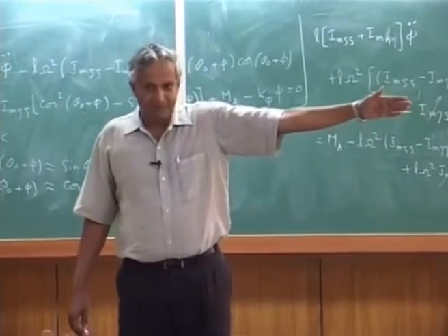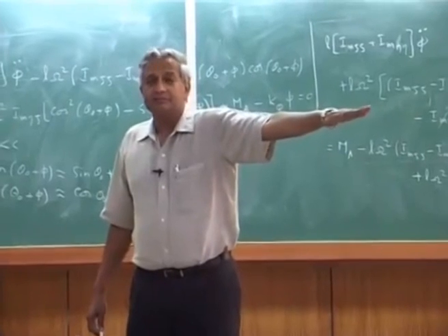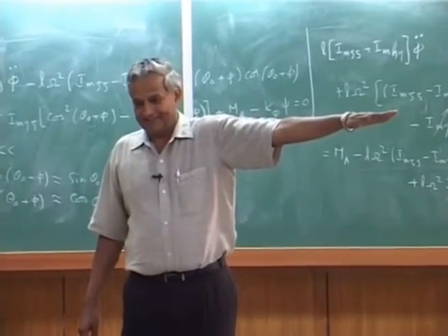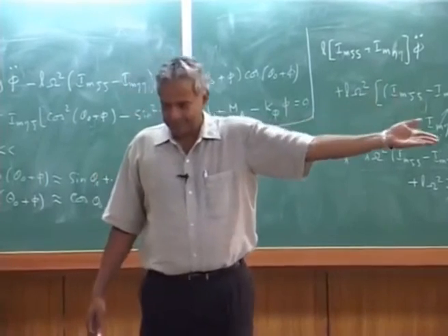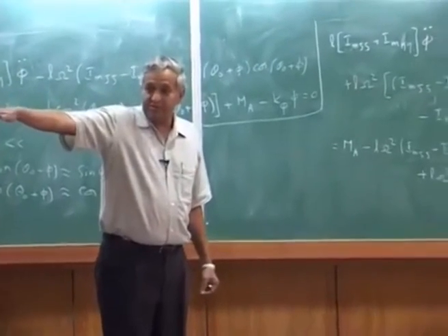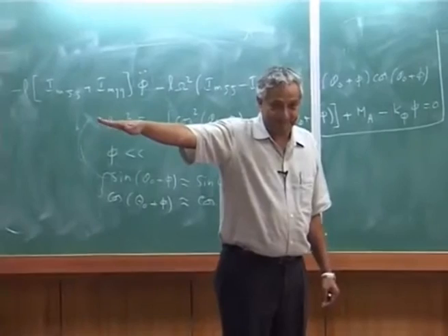In the sense, if you keep the blade like this and rotate it, the blade will always come down. It will be flat. Okay. That is a natural equilibrium position. There is always a nose down twisting moment because of inertial load.